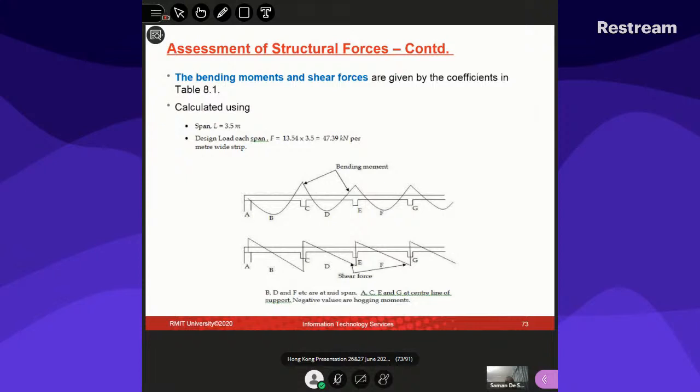Now you won't be able to do it manually if it's a continuous beam. Remember, there is a simplified formula given in Eurocodes and every code. This looks to me like the slab design, obviously. The slab is being supported by many members, so you can take a 1 meter strip of a slab and check that.